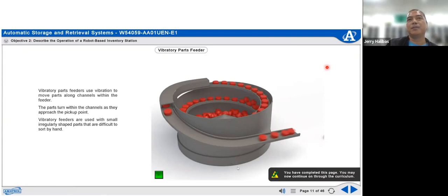For Danfoss, it's using ramp up and ramp down. For other brands, such as Allen brand, it's using acceleration and deceleration time. So if you set it to 60 seconds or 1 minute,